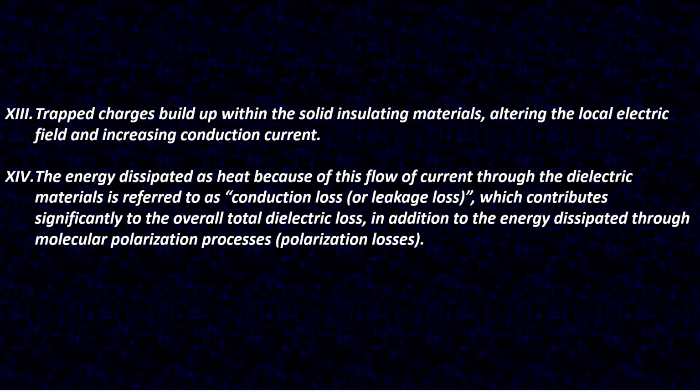The energy dissipated as heat because of this flow of current through the dielectric materials is referred to as conduction loss or leakage loss, which contributes significantly to the overall total dielectric loss in addition to the energy dissipated through molecular polarization processes, that is, polarization losses.